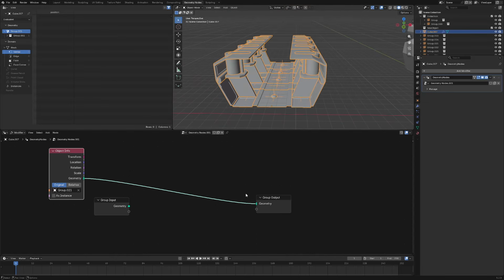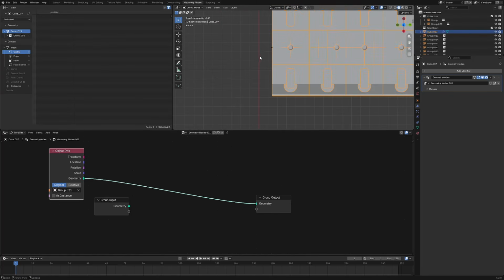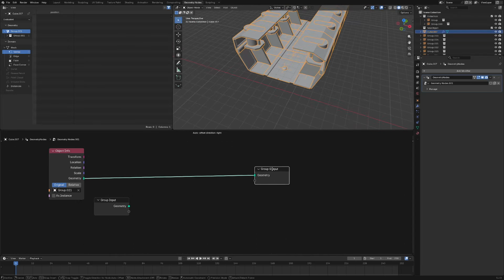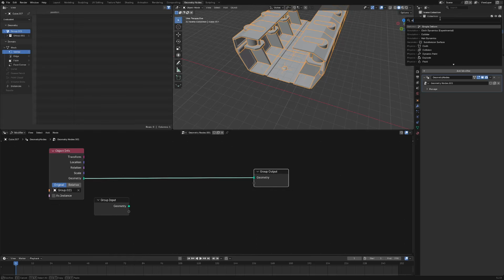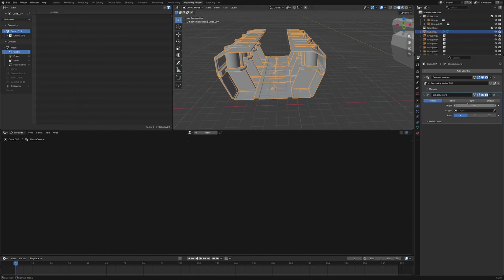Okay. So I don't know if you've seen how that exactly happened. Here's our origin point. It swaps it. Okay. And what we can do, as you can see, we can't add a modifier right now, but let's say we did a simple deform. Let's say we wanted to twist this whole thing. Okay. I'm going to try to twist it, and I add the twist, simple deform modifier, and I try to twist it up. It doesn't do nothing.